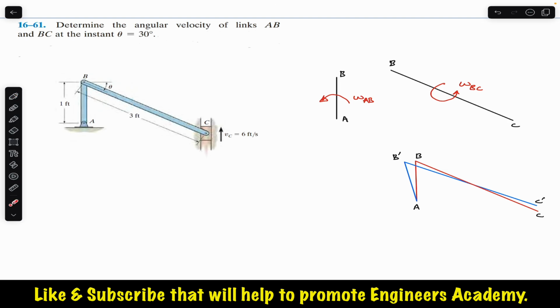Similarly, as we can see, this point B is moving relative to this point A, so point B will move in a circular path with the radius of this AB, and that velocity will be tangent to that circular path. So that velocity will be perpendicular to this link AB. So point B will be moving with the velocity VB in this direction, perpendicular to link AB.